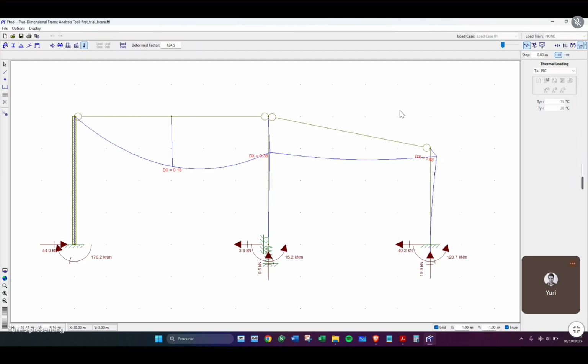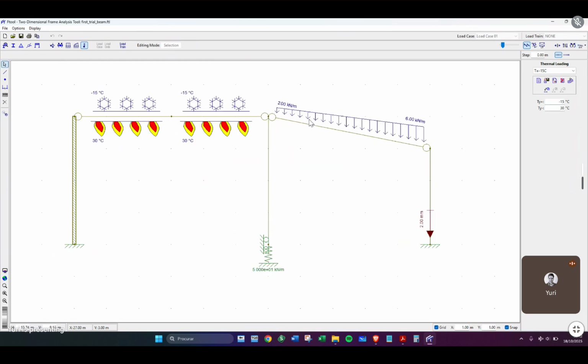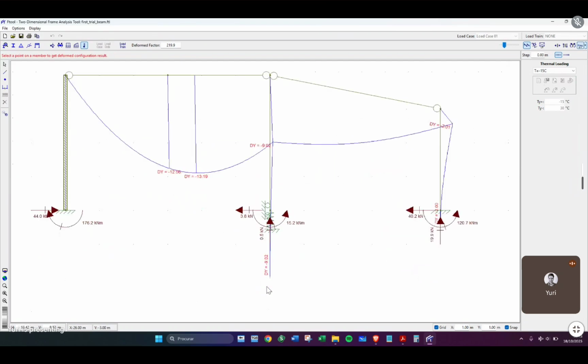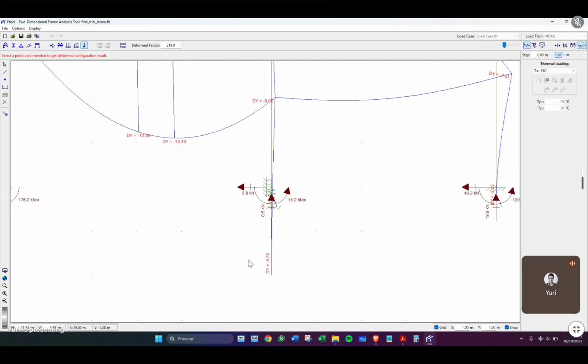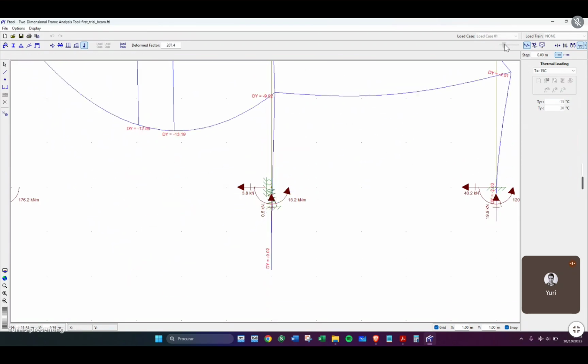Okay. So let's change a few things so you can actually see the results whenever we change some of the circumstances. Oh, I forgot measuring, but let's see how much it deformed here. So this frame here, because of the spring, deforms around 9 millimeters, which is significantly a lot.